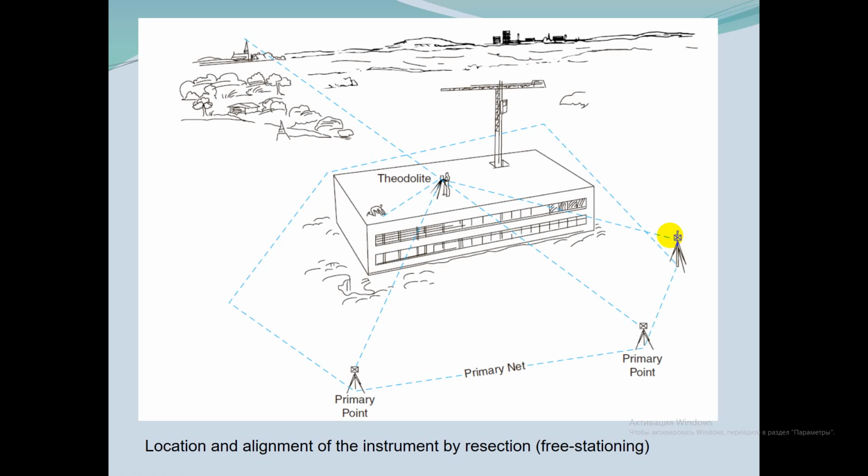Angles are then taken to a minimum of 3 coordinate control stations. A fourth control station could be taken to provide a second computation of the instrument station as an accuracy check. Both angles and distances are to be taken to the control stations.